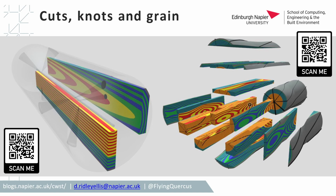So when you scan a piece of wood or a big log of wood and you decide how you're going to process it through a sawmill, it can be quite important. But all I'm saying is, do scan these later on and you'll get to see. What you'll see here though is the knots in the branch, in the log of wood. The X-ray machine will show you where the knots physically are and where the defects might be.